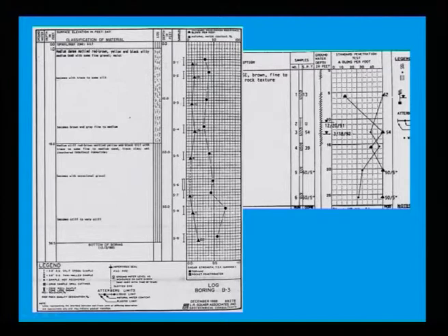If you look here, this triangle is your standard penetration recorded up to a depth of 36.5 feet. Instead of writing N, suppose here N is equal to 11, N is equal to 15, I want to show a plot of how it varies over the depth.